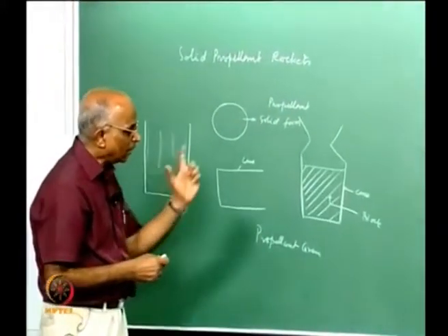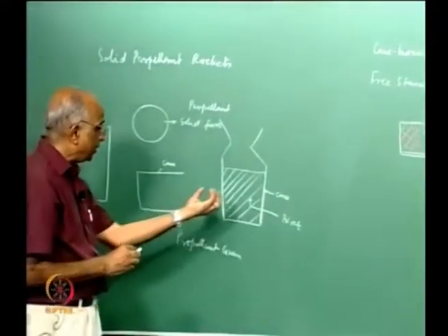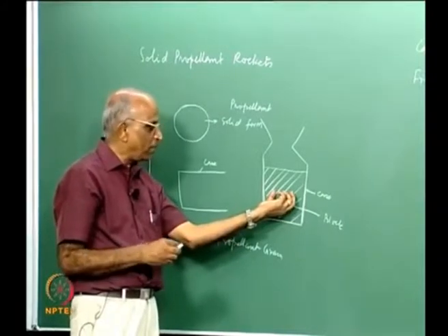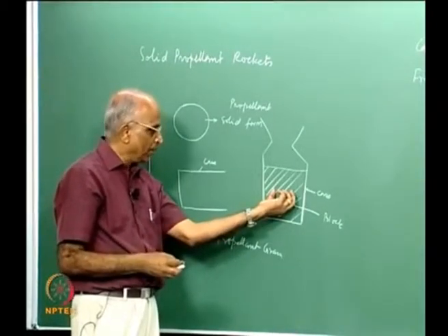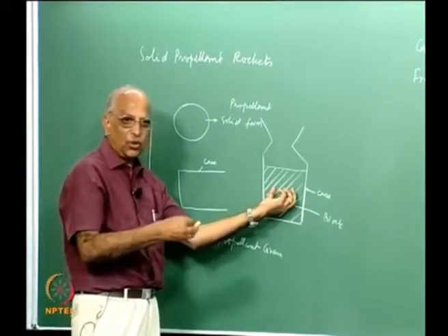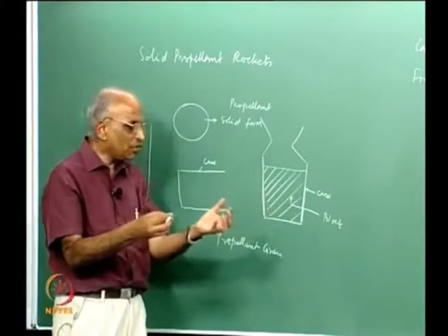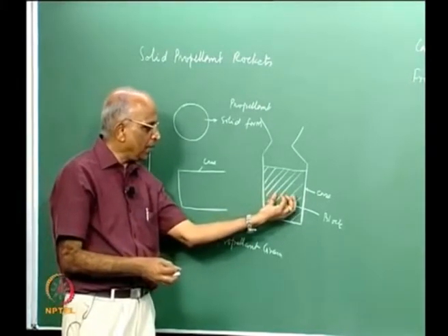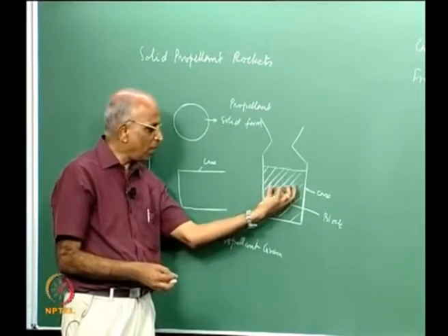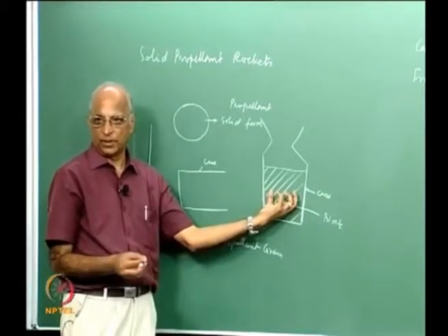Let's again look at the problem in a slightly different scenario, but before that, to repeat: if I have a composite propellant, like polybutadiene, which is a resin in liquid form, I put into it the solid loading crystals, AP and aluminium, and I have a slurry, a mixture of all these things. I heat it to a high temperature, form a solid block, and this solid block, when it is inside a case, is what is known as a propellant grain.